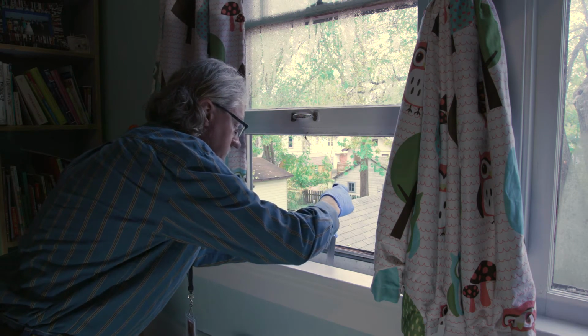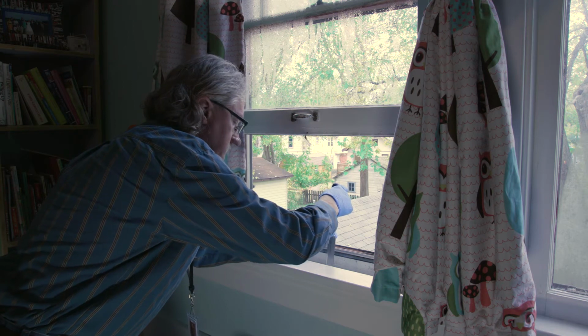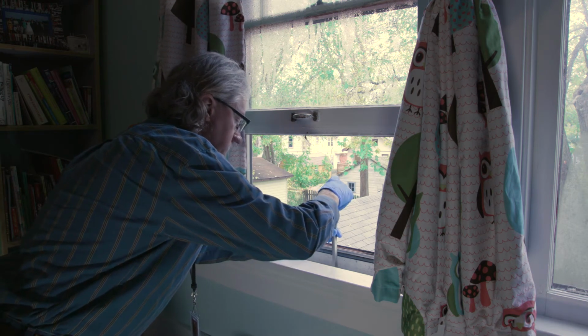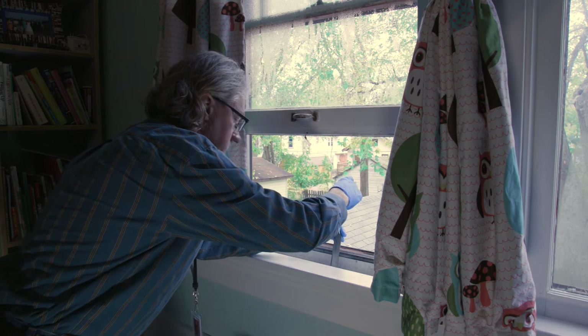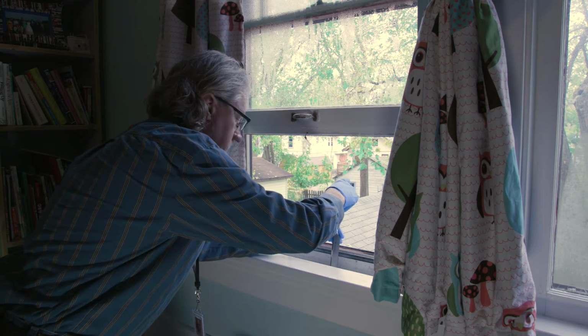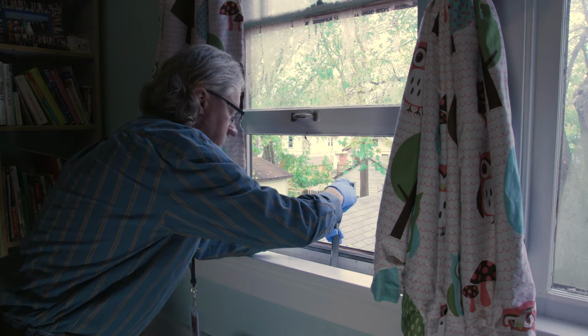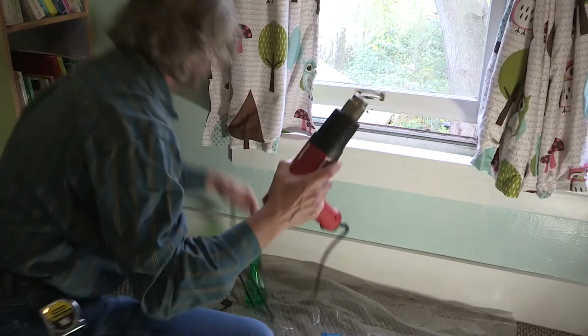Most labs want paint chips that are approximately 4 square inches in size. This can be achieved by taking a 2-inch by 2-inch sample or a 1-inch by 4-inch sample. Check with your lab for size and weight requirements of paint chip samples.